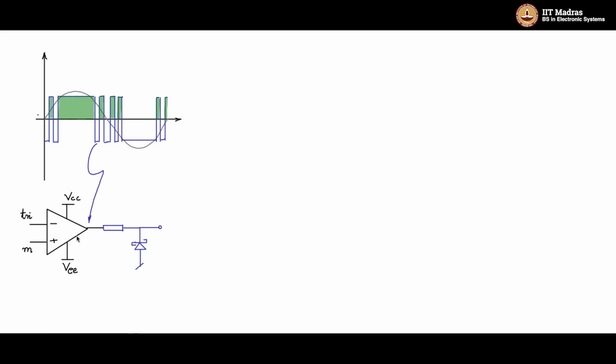So the op-amp will be sinking current at that point in time, into minus VEE. So the waveform here will be the shaded green portion. This will be the clamped waveform. You could also use a diode clipper and get a similar output, only the positive part of the output.